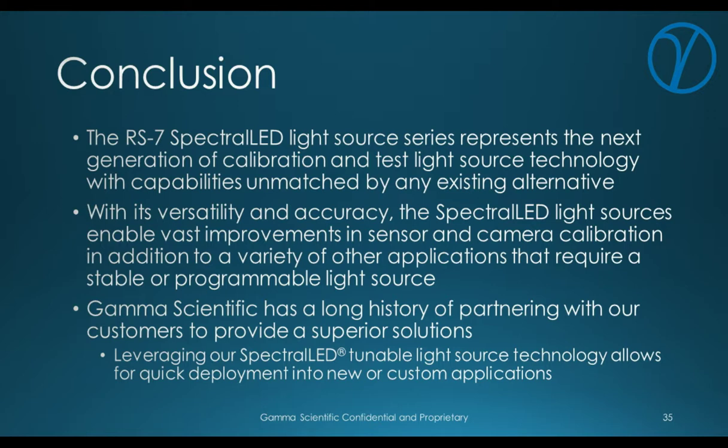We give you everything, and the thermal control, optical feedback, and the linearity of our constant current driver allow the accuracy to be unsurpassed by any traditional approaches that have been on the market. It also allows you to tune the spectrum and the color quite easily. In some cases, it might even replace a scanning monochromator for spectral responsivity type applications. It just makes it a very versatile and accurate tool.